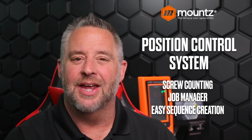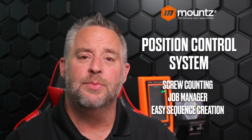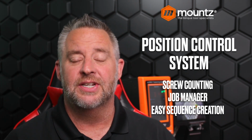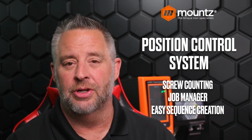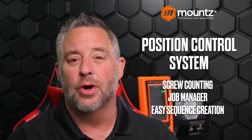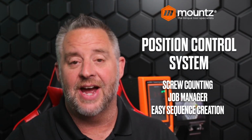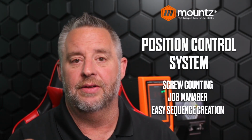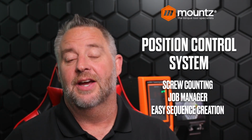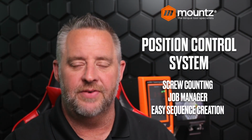If you have a high mix, low volume scenario where you may have different patterns that you need to use, the system has the ability to store different jobs. You can have up to 255 different fastening jobs. Each of those jobs can have up to 80 steps, and each fastening step within those 80 steps can have up to 50 fastenings.